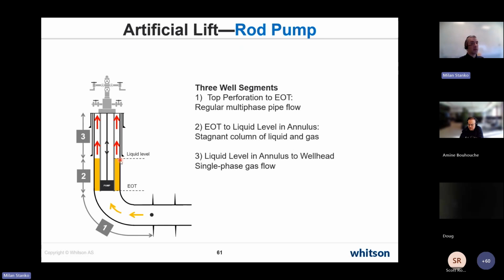That affects the density of that column. If we had, say, a 1,000 feet column, it is different if it is full of only dead oil or if we have gas through it. The gas will occupy part of the cross section, and the density will be less than the pure oil density. After we calculate the pressure at the end of tubing, we can take the formation fluids and that pressure, and calculate the pressure at the top of the formation.